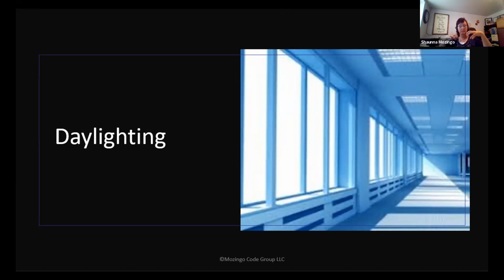This section is saying there are no people in the room, so the lights need to not come on. These daylight controls still need to respond to daylight, but they need to be configured to not overrule the occupancy sensors, to not increase the lighting power above the unoccupied set point.